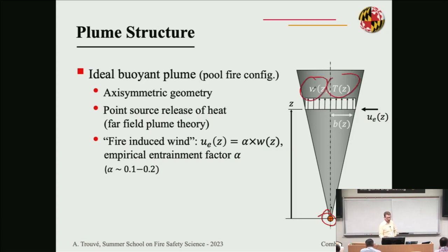And in this analysis, you have to introduce a horizontal velocity that is the air entrainment velocity. And it's very important to understand mechanistically, I mean, people who are doing flame mechanics shouldn't be surprised that when you have strong buoyant acceleration in the vertical direction, you must have some horizontal motion and bring air into your flame or your plume.